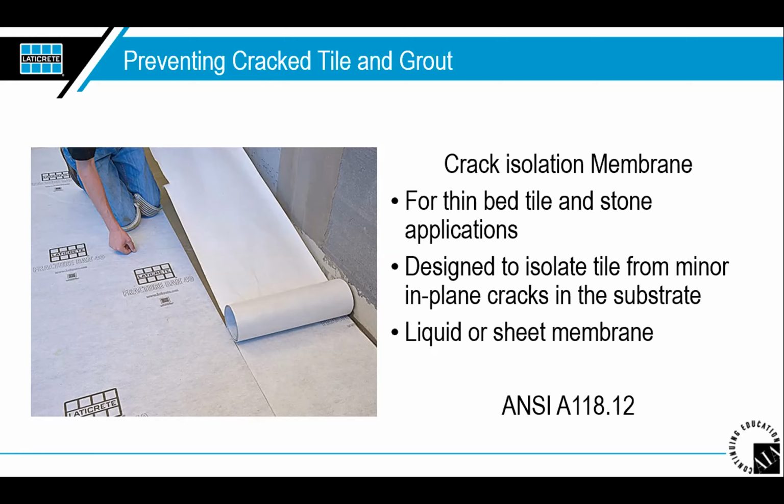But if you do these Band-Aid type methods, they may not be doing them correctly. A lot of times they're going to require you to actually use like 3 times the width of the tile whenever you treat these types of cracks. And if that's the scenario per the manufacturer's instructions, think about it. Let's say you're in an office building where you're using a 24 by 24 inch tile. That means that Band-Aid you're supposedly putting on the floor technically would need to be wider than 6 foot. Well, if you're going to do one crack or 2 or 3 cracks, chasing them at 6 foot wide, why would you not just do the entire floor, right? Whether it's liquid applied or a sheet membrane type of material.